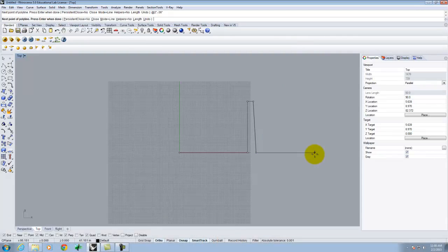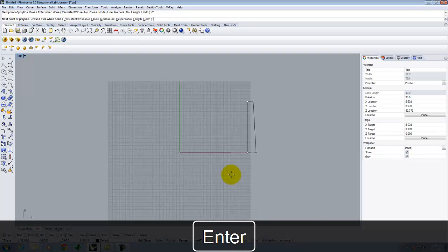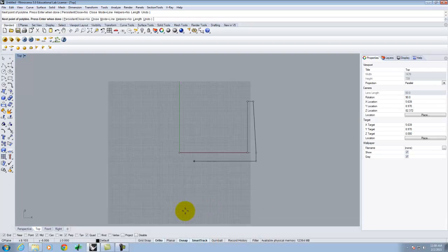This is why I want to overemphasize the use of these coordinates, because on certain objects that you're trying to draw, the most efficient way of doing it is to use the relative coordinate system. Okay, so I just did that, and we'll continue. I'm going to go down 6 inches. So again, I'll do it in direction. There it is, down. Now, once again, I am going to go over 30 inches here, and I'm going down another 6 inches. So once again, an opportunity for a relative coordinate.